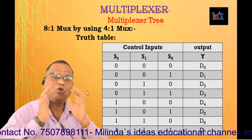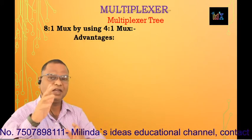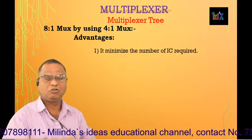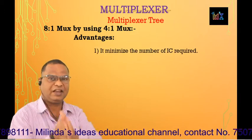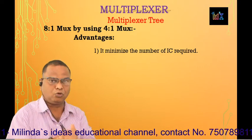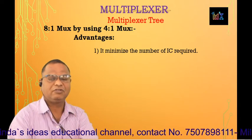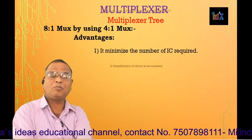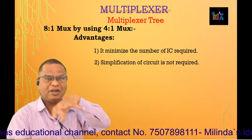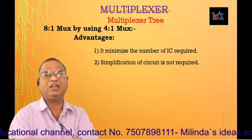Now, what are the advantages of this multiplexing tree? First of all, it minimizes the ICs required. In this case, it is a 4:1 mux, so a single IC 74153 can be used to connect 8 inputs to a single output. So the number of ICs required can be minimized. Second, simplification of the circuit is very simple. If we wanted to simplify it by using Boolean laws, Boolean algebra, the simplification of this circuit can be easy.